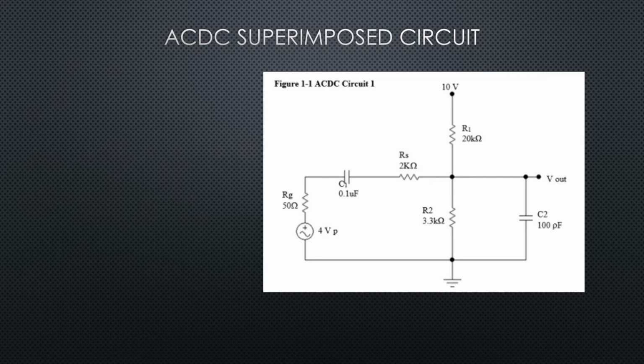Right? So now we've got all the DC, the AC, we've got the low frequency voltages and or response, and now we want to find the high frequency cutoff. So we're talking right here, and we know that that's going to be impacted by C2. We know that at this frequency, C1 has been shorted for a long time, so it should have been shorted. It is shorted in the midband. So our redraw, or our Thevenin C2, would look like this.